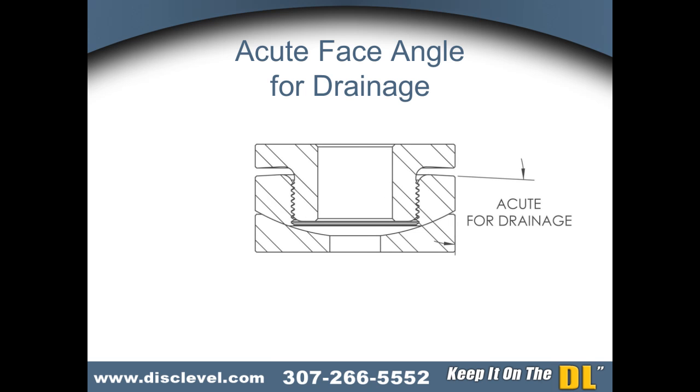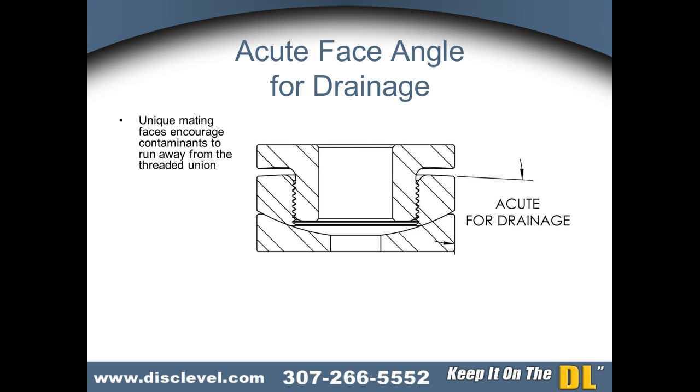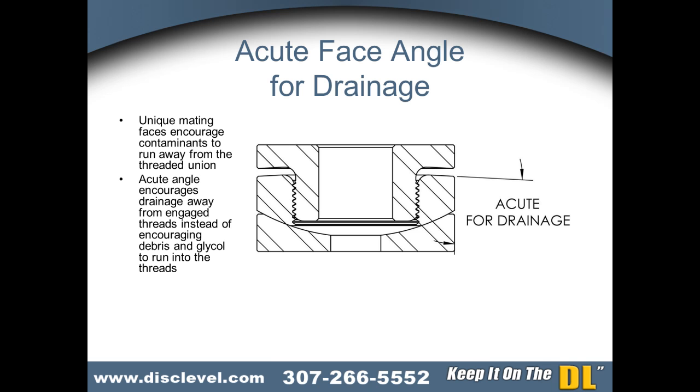Acute face angle for drainage. Unique mating faces encourage contaminants to run away from the threaded union. Acute angle encourages drainage away from engaged threads instead of encouraging debris and glycol to run into the threads. Concave surface also encourages drainage.